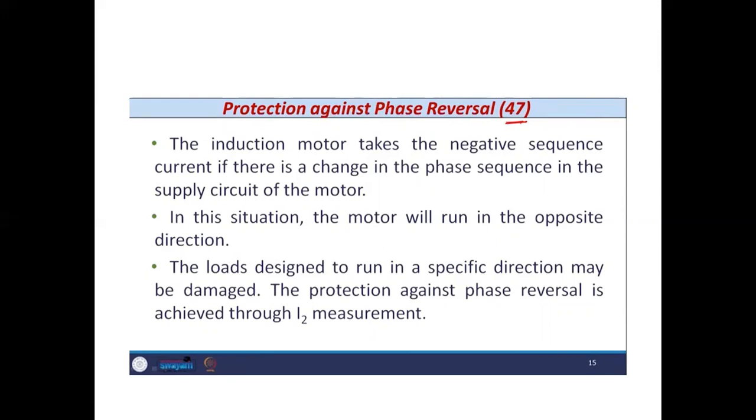So if the motor runs in the opposite direction, then whatever load you have connected will be damaged. So protection against phase reversal is very important, and this is once again achieved with the measurement of negative phase sequence current, that is I2.